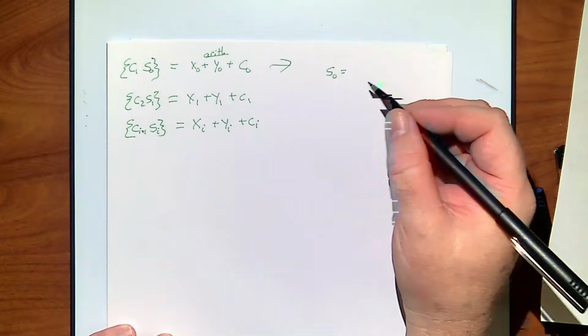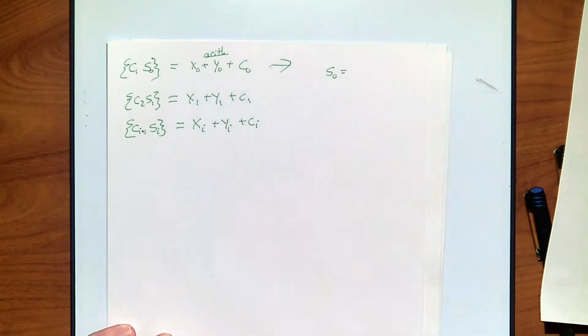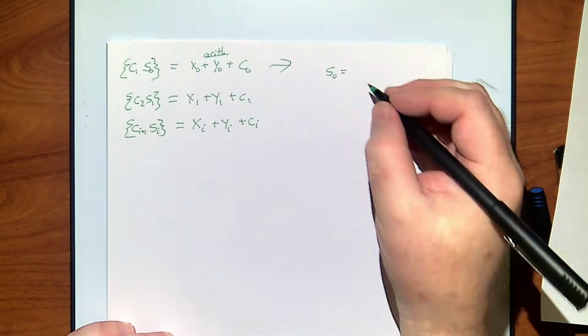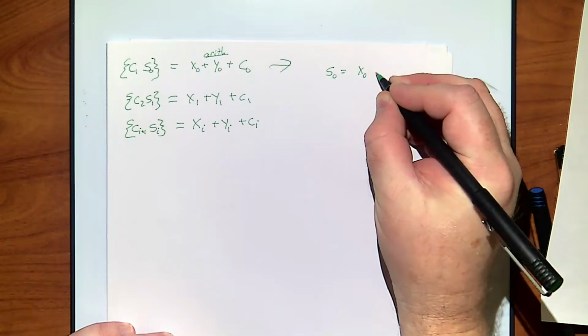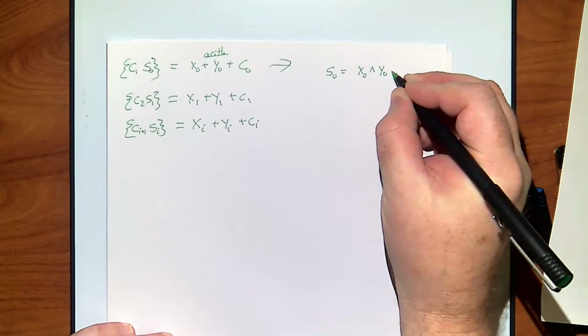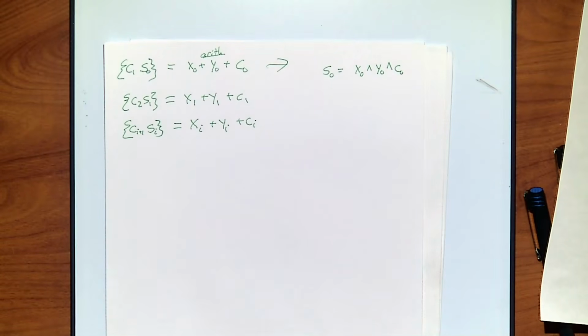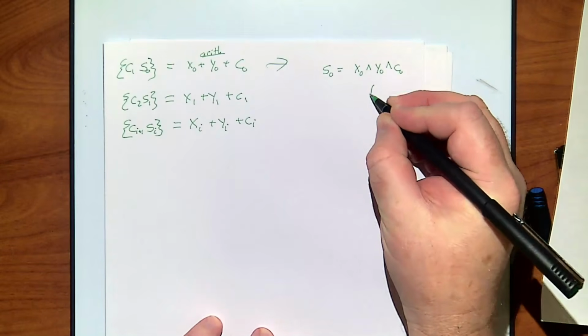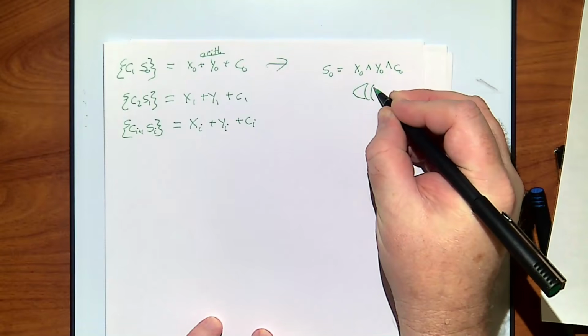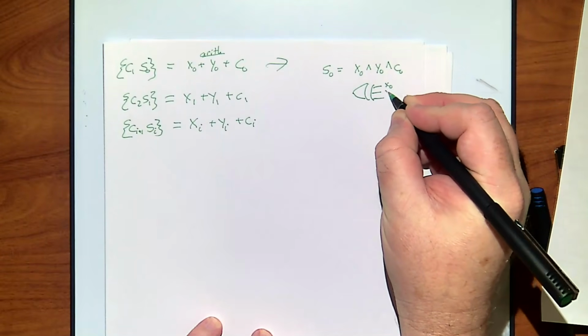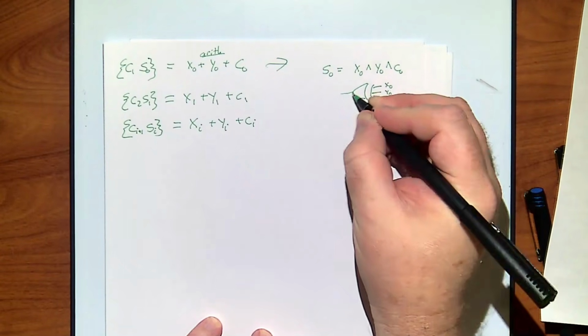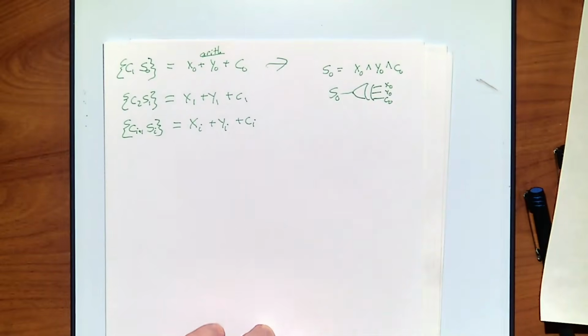So we've got XOR to get our sum, right? Because XOR is odd. So I can say X0 XOR Y0 XOR C0. I believe I can do a three-input XOR. This right here just looks like X0, Y0, C0. Boom, here is S0. Right? It's one gate. I don't have to do it in stages with half adders.